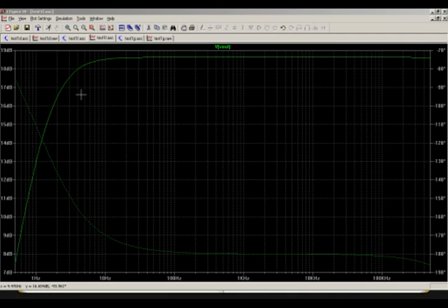In the resulting frequency response, we see here a breakpoint at about 2 Hz. So this is minus 3 dB. Also a small phase shift here from 20 to 100 Hz. So normally we have a 180 degrees phase shift because it's an inverting amplifier. At the high side, the 20 kilohertz is very good.